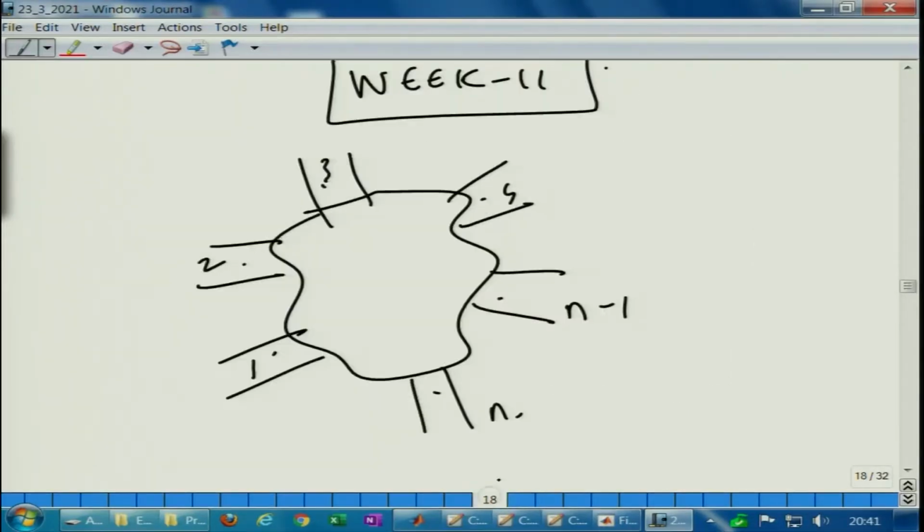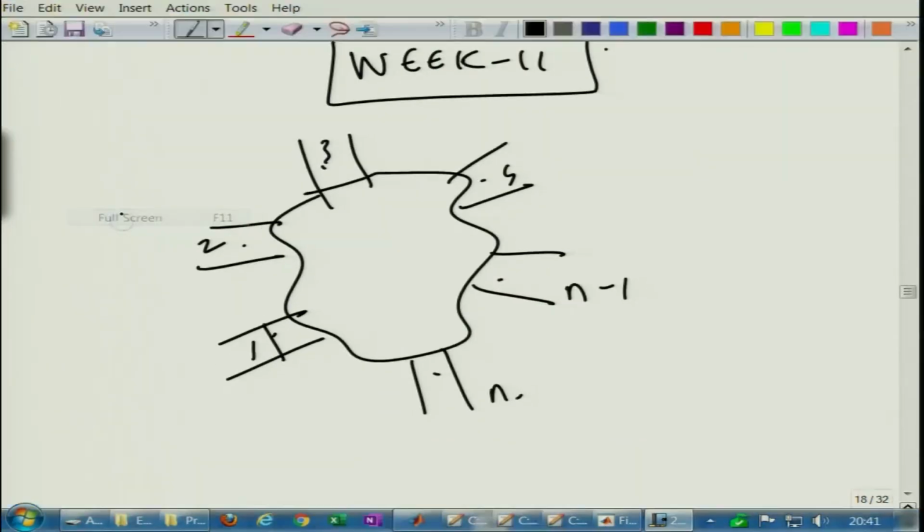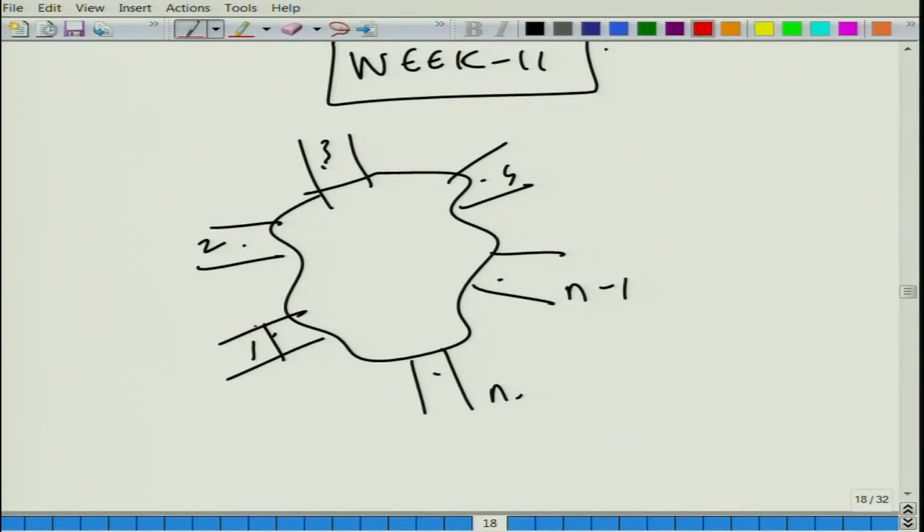Let us go back to our schematic or the line diagram. So, what we do, let's say we excite the system by means of some kind of a piston excitation somewhere here, a to and fro motion. We generate waves, we block all the ports here, or you could also block it elsewhere, so that the effect of sudden expansions at these ports might also come into effect.